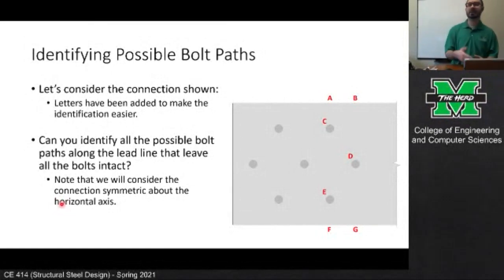In tension member analysis, we're going to consider both cross sections, the gross section and the net section. For each one of those sections, we're going to compute a capacity. So there's going to be a capacity in the gross section and a capacity in the net section. And if we want to express how strong that member is, we're going to take the lowest, the one that governs. If I yank on it, which is going to happen first.